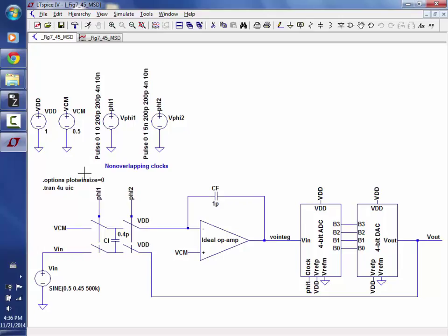So now here's the problem. If you can make a precise DAC, it has to be as precise as the final resolution. That's easy to do with 1 bit because you get 0 volts or 5 volts or whatever your VDD is. If you have to make a 4-bit DAC that's 10-bit accurate, you're kind of defeating the point of using noise shaping techniques. So I need to take the water out within 10-bit accuracy, right? It's easy with 1 bit. It's empty or full. It's not easy with a